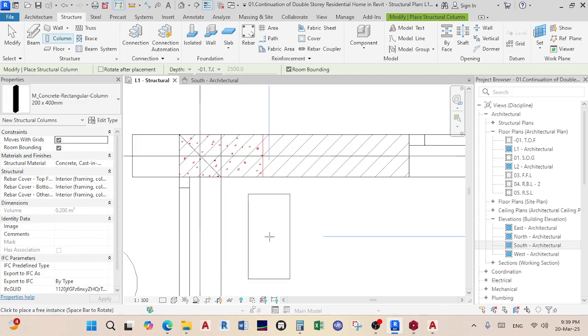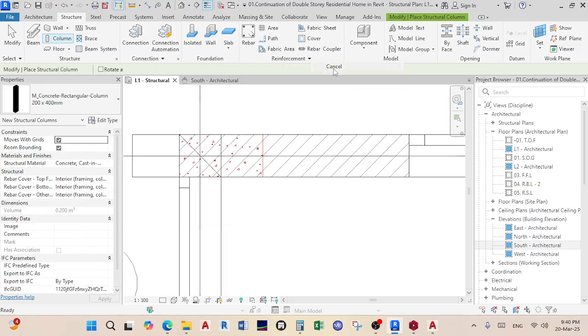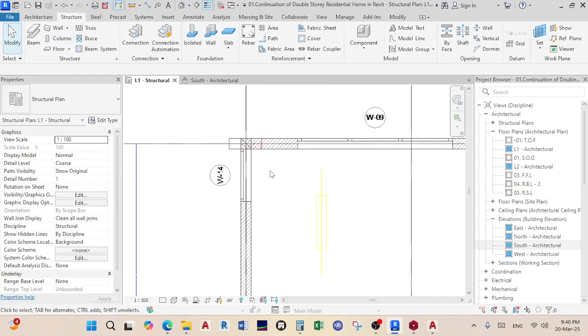And the good thing about Revit is that I can actually place it at 45 degrees. For example, you see I'm changing in a white space, right? But if I take it here by the corner, it will actually do that. You see it gives it a slant, like a 45. Pretty cool, right? So take it back to my white space, and then I'll place it there. So you might not see it, but I've inserted a column.